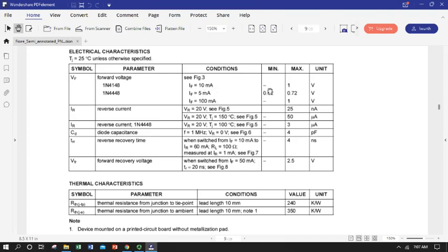But for a middle of the road, you've got a min-max, you've got a range of somewhere between 0.6 and 0.7 of a volt. And this is characteristic of a silicon device. The 0.7 volt forward bias is pretty typical. And if you're not told otherwise, that is a good number to assume if you don't know. If you don't know what type of diode you have, you can usually assume it's silicon unless otherwise specified. And you can assume it will have a forward bias voltage of 0.7. And we'll see what that means in a circuit in the next section after we create a model for it.